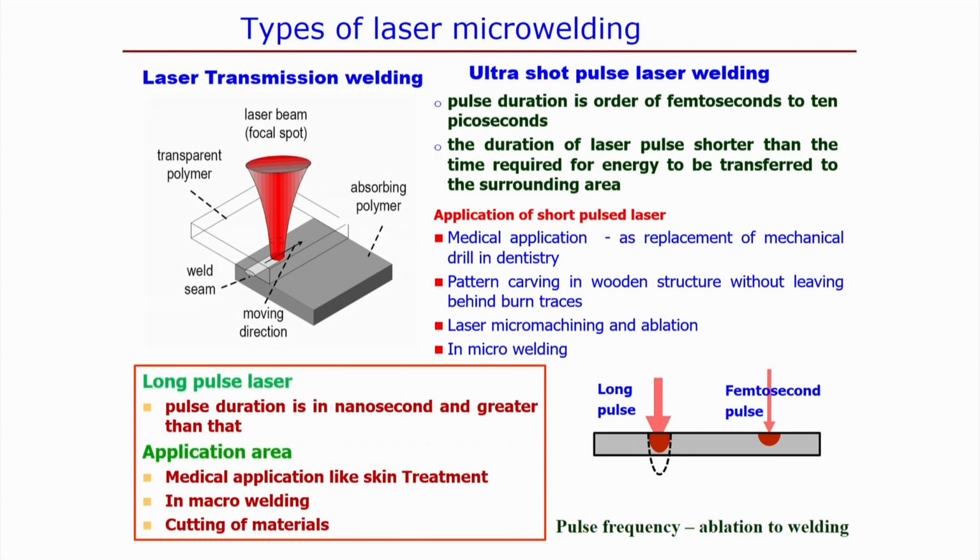Normally, this ultra short pulse laser welding we analyze using non-Fourier heat conduction or two temperature models, assuming that there is phonon and electron scattering or coupling, or scattering between phonon and phonon. Based on those principles, we can estimate the different relaxation times when a substrate material interacts with an ultra short pulse laser, that means any femtosecond pulse laser.